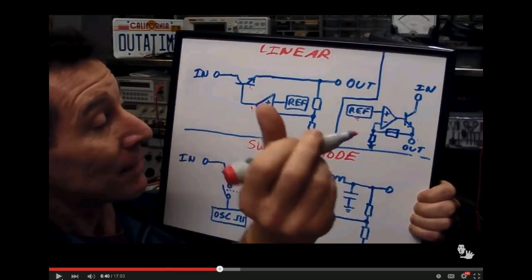Yeah, he does. And of course, we don't have time. We have 2 electronics courses, we don't have enough time to get into op amps in this class. We have an advanced electronics course that should be in your list of electives if you decide to take that. And we spend a lot of time with these devices called op amps. But you hear what he said? What the op amp is trying to do is keep these 2 inputs equal. So this one comes from a feedback, and then we put in a reference. And this guy's going to drive this output to make this input equal. Does that make sense?